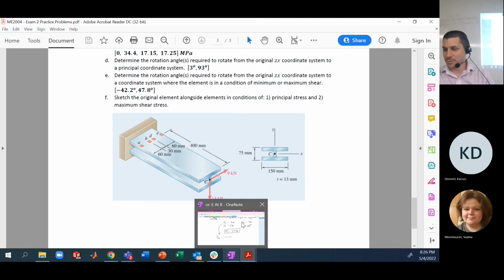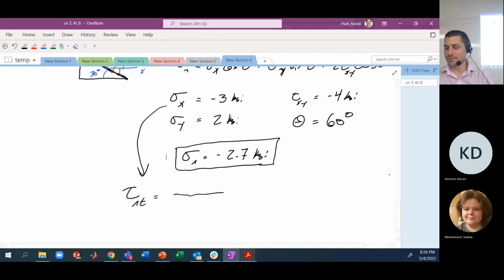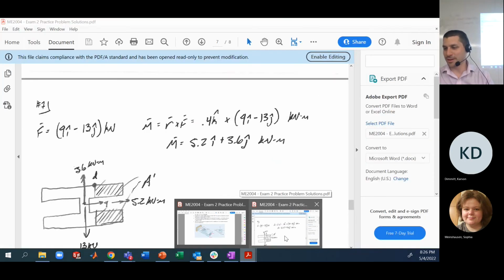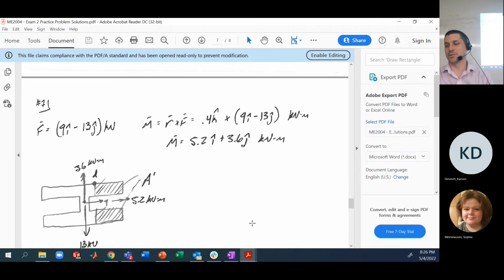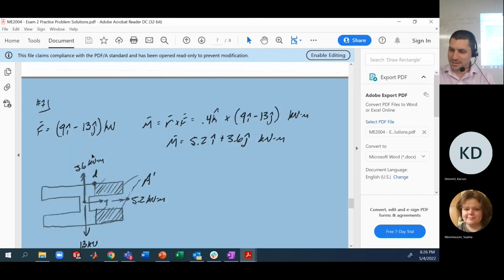Strangely, in this problem, we do have a situation of bending about both the X and the Y axis, which will contribute normal stress at D. This goes back to the eccentric loading that we talked about at the end of the bending lecture, where if you have some point that is both off the Y axis and off the X axis, then you could have contributions from both MX and MY that provide normal stress. Got it?